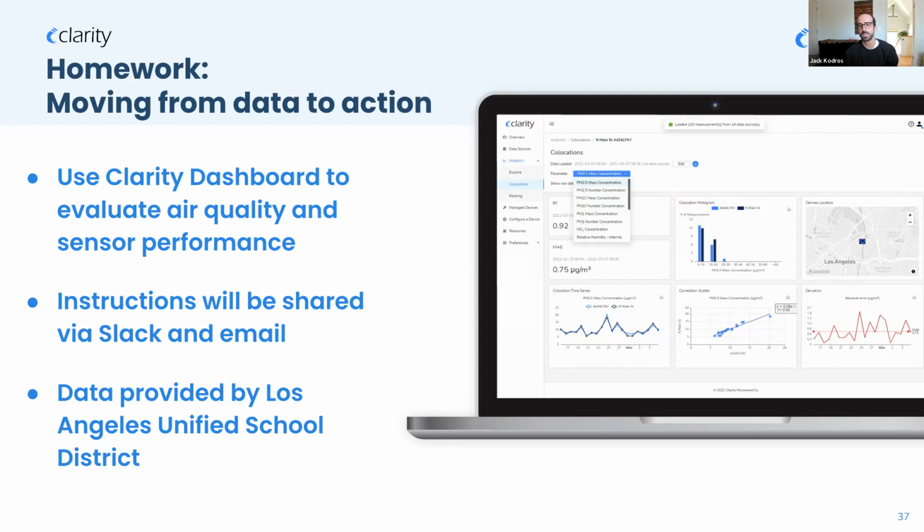Yeah, sure. It really depends on the type or which pollutant we're interested in the spatial distribution of that pollutant. PM2.5 tends to be a little bit more regional over a city, whereas NO2 often varies block by block. NO2 is highly related to traffic, so you will have much higher concentrations by a road as opposed to a park. Ozone is a secondary pollutant and is much more regional, so you may need fewer ozone sensors in a city compared to PM2.5, where you need slightly more, and then even more for NO2.